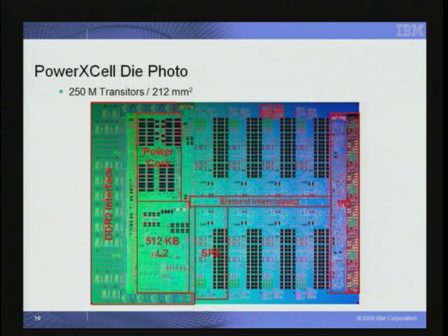This is more or less the original memory controller area that we made some modifications to, but not too many. Then, roughly speaking, the SPE bounding box is here, and right there is an EDP module, which I've shown there. So in some senses, given the DDR2 interface and the chip growth that was required to bolt that on, the enhanced double precision is slipped in for free.